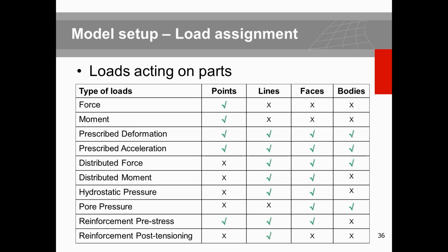It calculates the column of the water or the fluid and calculates the hydrostatic pressure for you. So you only need to say what is the height with respect to the reference, then the program considers that from the reference to the height that you defined, there is water, and it automatically calculates the triangular or wedge type of pressure for you.